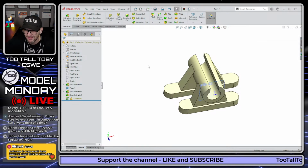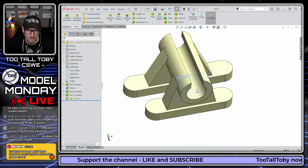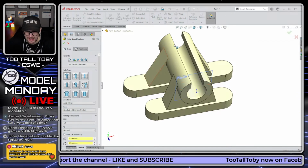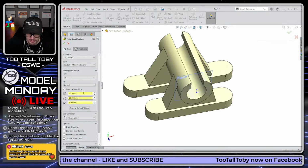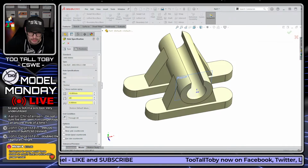Thank you so much. So now that we've got that pattern created, we can go and choose the option for Hole Wizard. I see I've got an error in the tree. I'm not going to worry about the error just because I'm running up against the top of the hour. But that Hole Wizard hole is going to be 10 millimeters through, 20 millimeters counterbore, 5 millimeters depth.